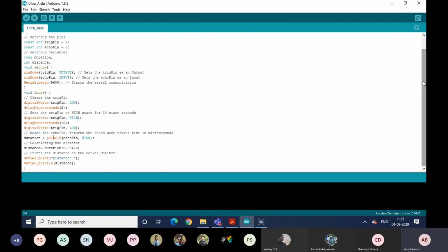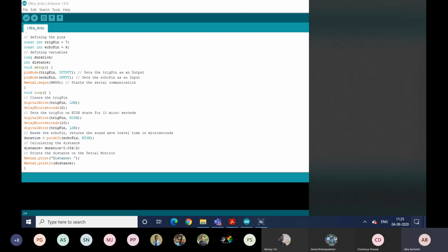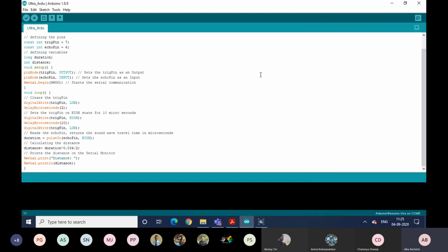It's very simple actually. No header file is required here. It's a simple sensor where we use the trigger and echo pins. Trigger acts as an input, where we provide a high pulse to activate your sensor. Echo is what transmits and receives the ultrasonic signal. So only these two pins are sufficient.